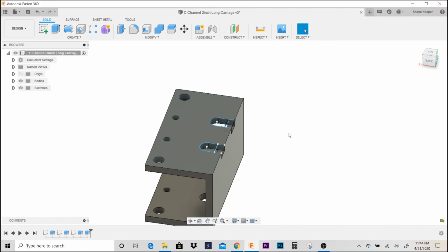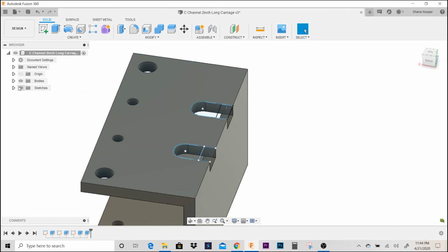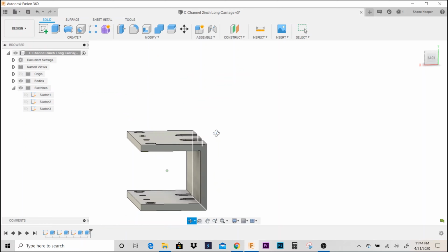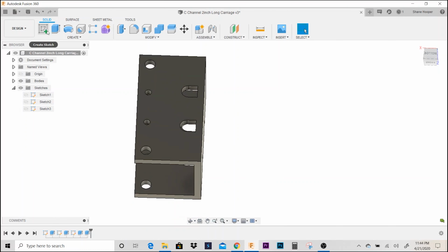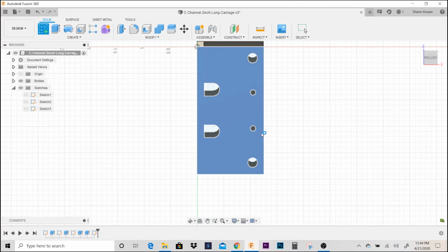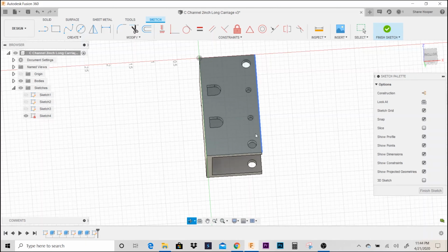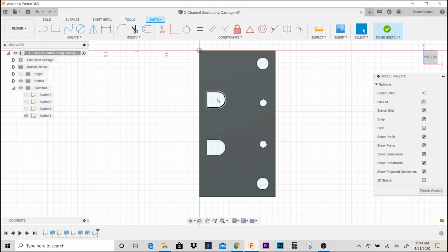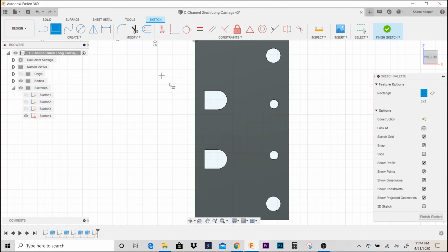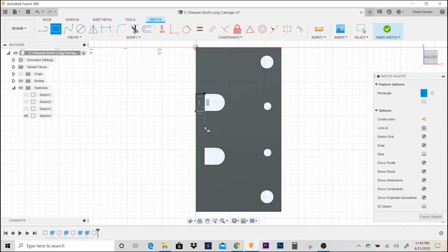Now notice you still see my geometry lines, right? That's because if I click my sketch, you can see it's shown right here. It's got the little eye symbol, so I'm going to click that, hide it. Now if I want to, I could just go back over here to this side. Go to rectangle. I could click on the edge of this, kind of hover right here, bam.